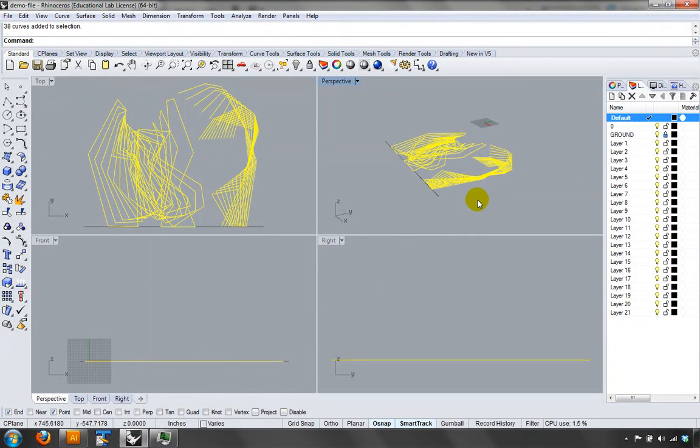And once I've got that, I'm going to type in the command for rotate 3D, ROTATE3D, because we want to rotate this in 3D space. We want to basically take this and, like you're raising a barn, like seeing an Amish barn raising. They would build the side of the barn on the ground, and then a bunch of Amish people would raise it up from 0 degrees to 90 degrees so it's upright. That's what we're going to do. We're going to raise this barn here.